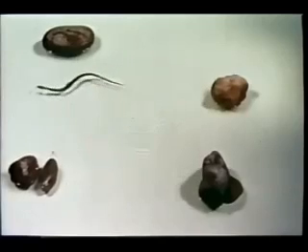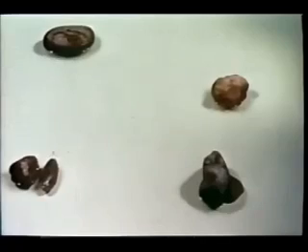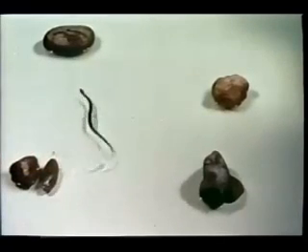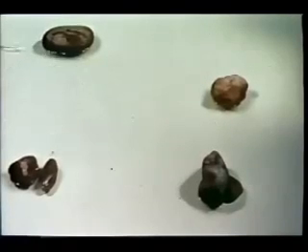Microscopic creatures, which may have Reynolds numbers as low as 1/10,000, cannot derive any appreciable thrust from inertia. They rely on moving their bodies in such a way that they derive their thrust from viscous stresses.